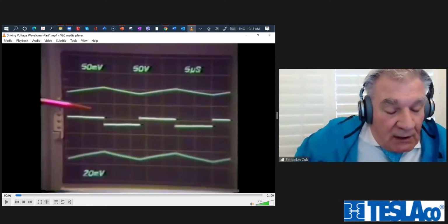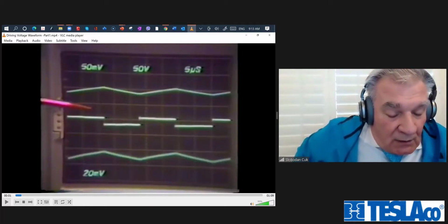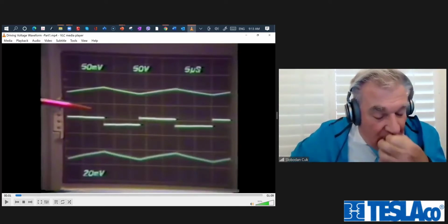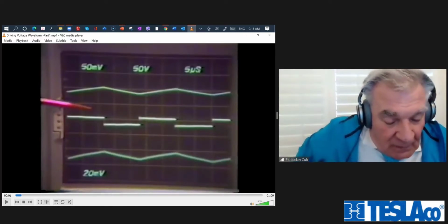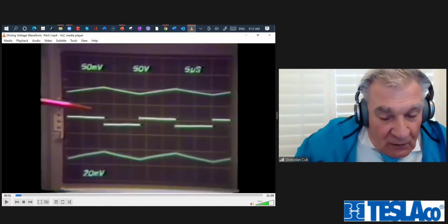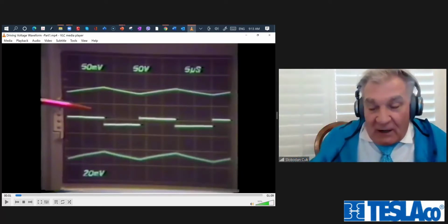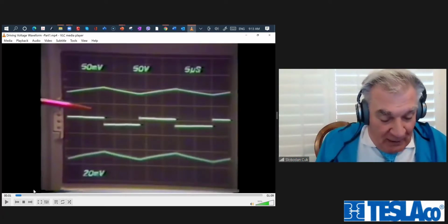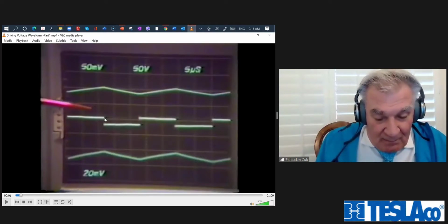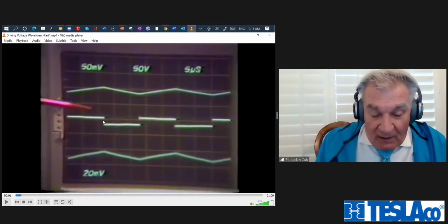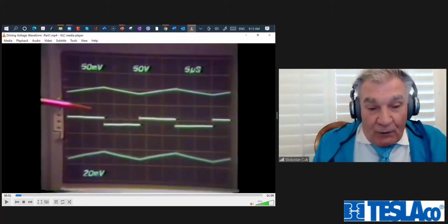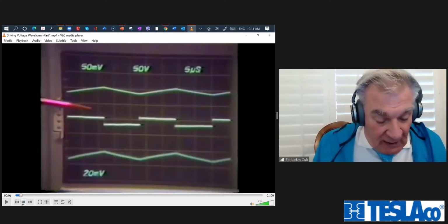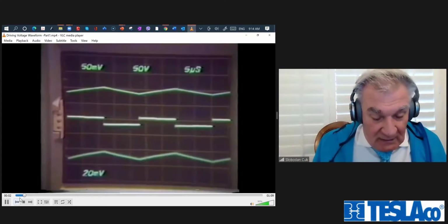But if I measure the current in the primary, and with a smaller current sense winding or so on, I can observe the current driving the core, and I can observe the flux in the core. Now, my standard question, when I want to challenge you: they both look linear, right? But if I start increasing the magnitude of the drive, and remember, the drive is now 50% positive voltage, negative voltage with a zero, so it's a volt-second balance, flux balance. But if I increase the drive, then what happens?